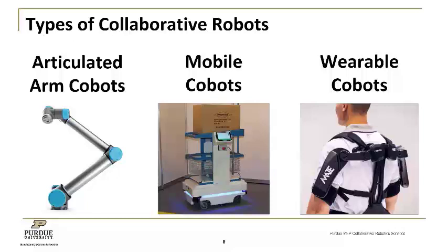The third type of cobot falls into the wearable robot category. These are more commonly referred to as exoskeletons, and they're designed to reduce muscle fatigue and help with ergonomically challenging tasks. Now, there are different exoskeleton models. Some use spring-actuated motors, and some are actually electrically powered with lithium-ion batteries. These are very useful for things like overhead assembly line work.